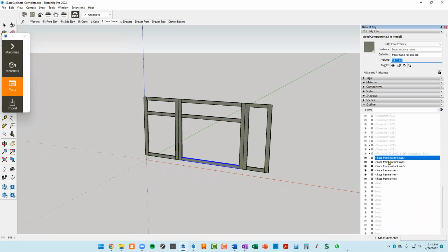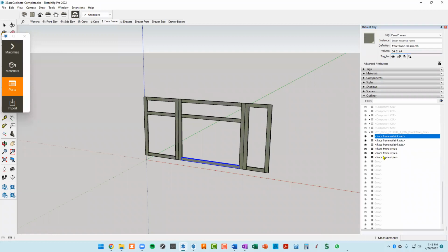So basically, it's a little bit of a pain in the butt. If I knew we were going to use this OpenCutList in the beginning, I would have named all my components while making them. So it kind of steered you in the wrong direction there. But if you want to go through this exercise, it's a little tedious, but I would recommend just doing it on new models to start with. But anyway, so that's one thing you've got to do. You've got to name your components.